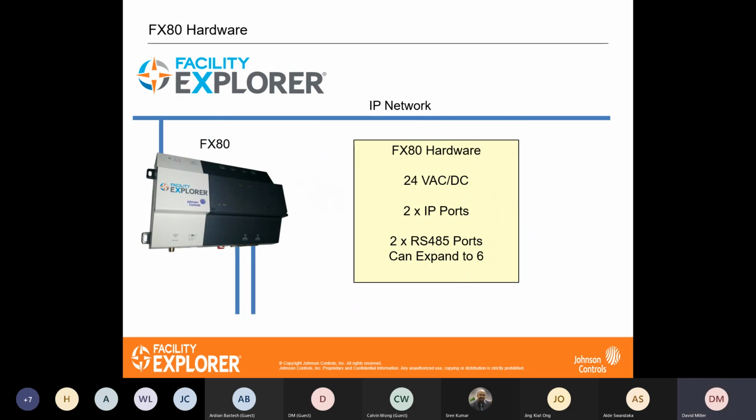So the FX80 requires a 24-volt AC or 24-volt DC power supply. It has two IP ports, so it can connect to two separate IP networks.